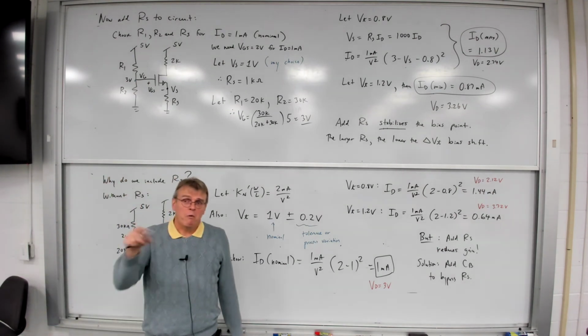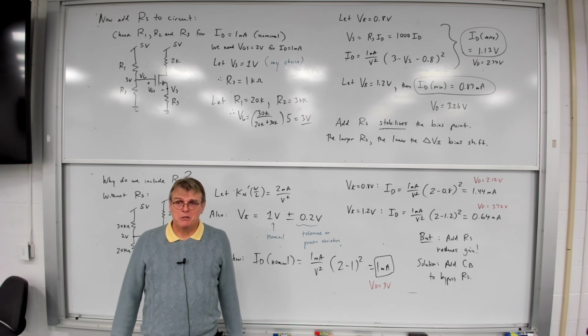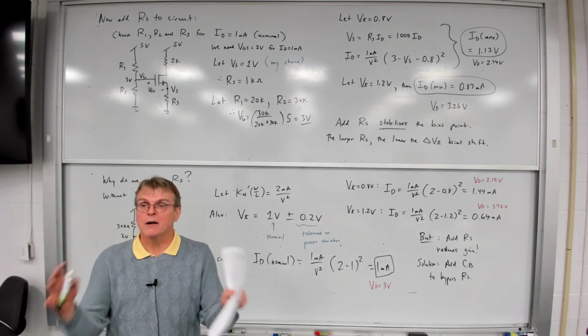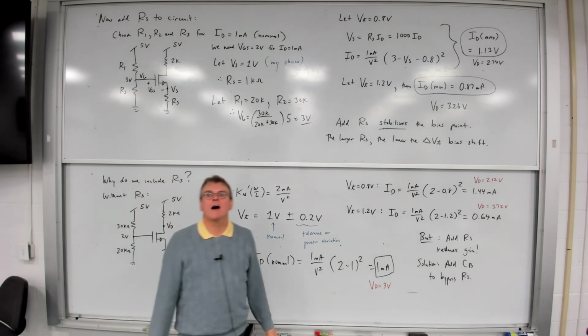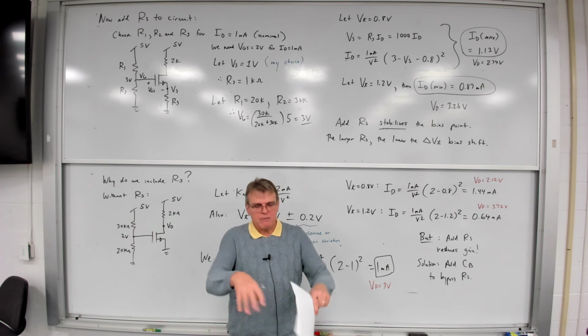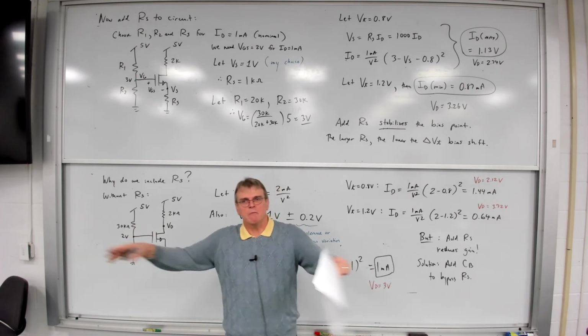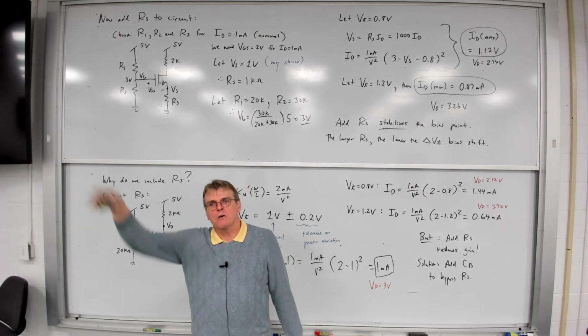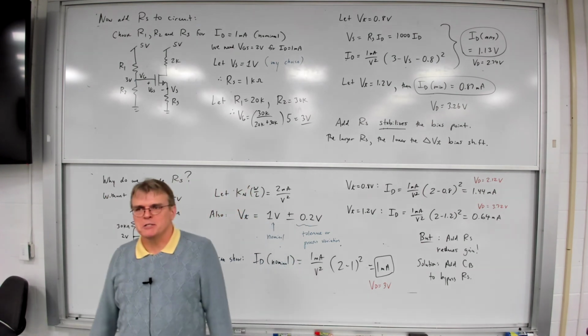So one of your last labs this semester is what's called a Monte Carlo analysis, where you're actually going to use LTspice and throw in the tolerances. You're going to run the Monte Carlo and tell me, given all the tolerances, if we look at random variations for all the components, what is the range of gains? Or what is the range of bias points you get out of the circuit?